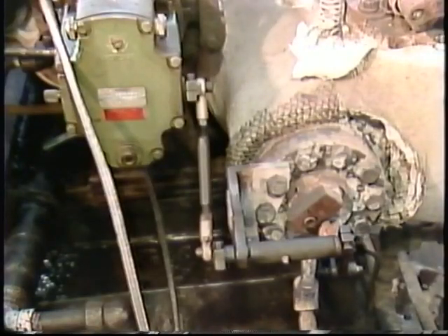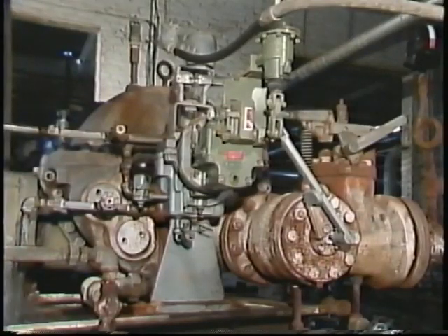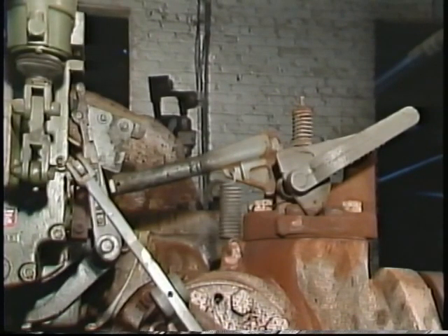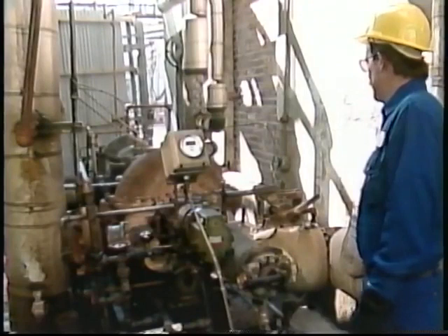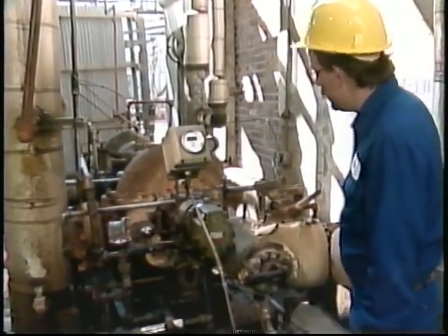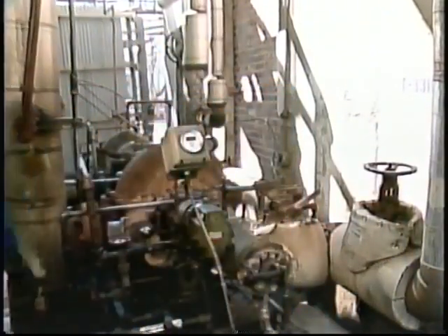In the turbine's speed control system, hunting and overspeed are conditions to watch out for. Hunting, as we discussed earlier, is inefficient. Trips from overspeeding are also disruptive and costly. Although, of course, if the trip mechanism weren't working to stop the turbine during overspeed conditions, the cost of the facility could be even greater. Observing the operation of the speed control and the turbine protection systems during your routine inspections can help you determine if the turbine is running normally.